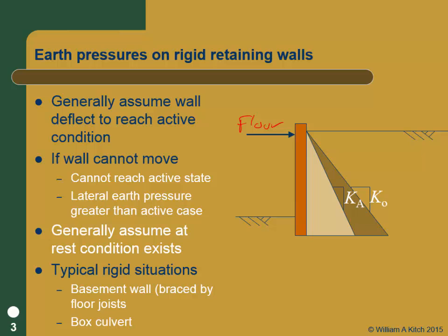But if you've got a rigid wall and you compact the soil heavily behind the wall, you could get as high as, what's the upper limit you could get to? The passive earth pressure. And that's a big number, right? You go from 1/3 to 6, that's a lot. So we need to understand compaction earth pressures as one.